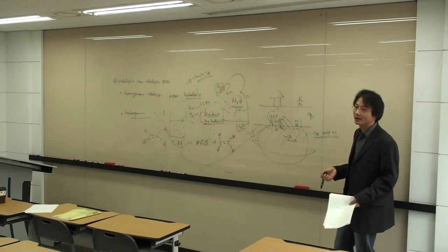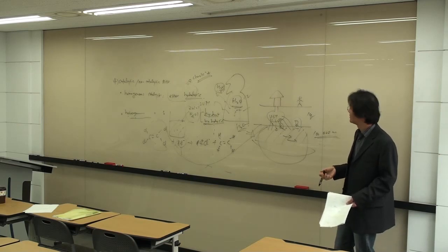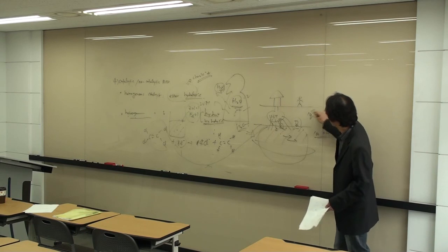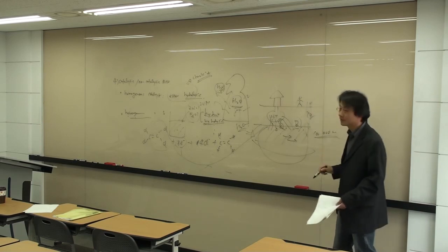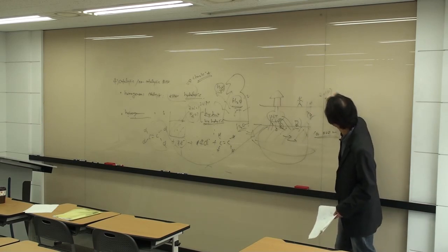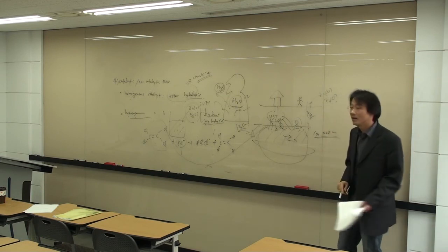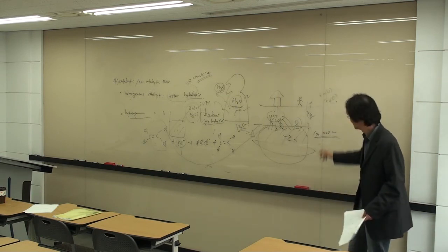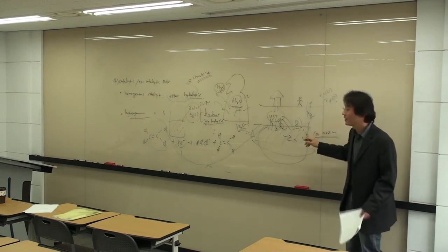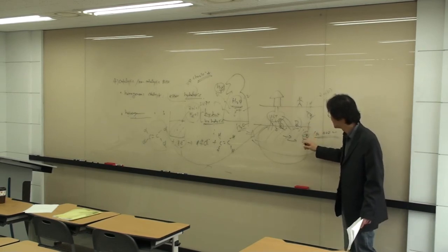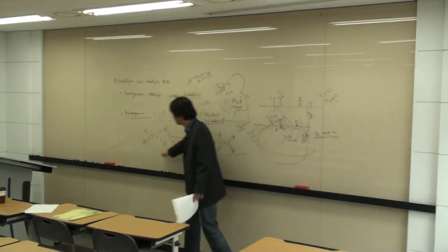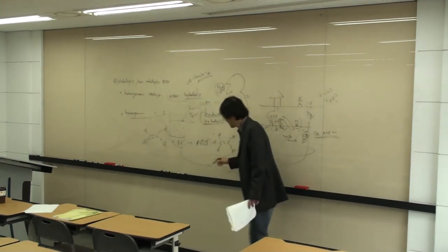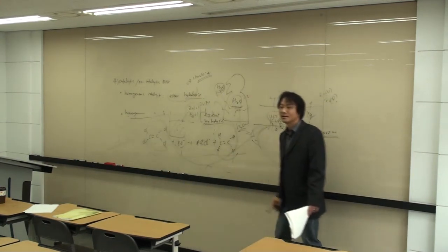One interesting remediation technology is just drill this and then make a big hole and then just put the zinc or Fe0 suspension into the ground, and this can be easily mixed up here, and this chemical can have this kind of reaction, and then you can have this non-toxic chemical.